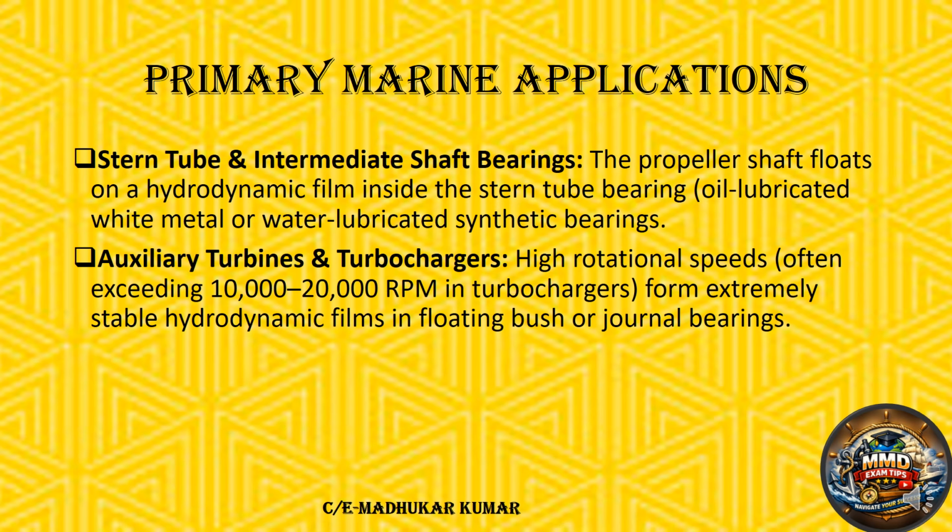Another primary marine application is your stern tube and intermediate shaft bearing. The propeller shaft floats on the hydrodynamic film inside the stern tube bearing, an oil lubricated white metal bearing, or even a water lubricated bearing. So the stern tube lubrication also comes under the hydrodynamic part, because the propeller shaft turns and it does the same thing, that journal and bearing separation.